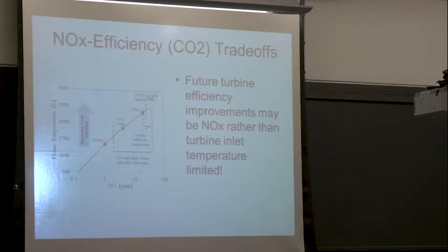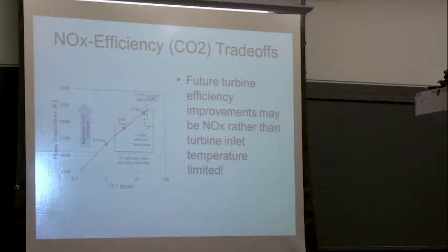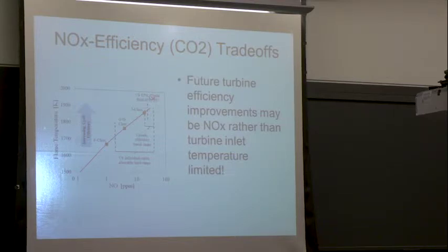And so now I think this is a great combustion problem: how do you turn off Zeldovich? So those of you who are doing high pressure, high temperature kinetics, what is it that you can do to somehow fundamentally change that sensitivity to temperature? Because, all right, well, let me just tell you, let's suppose I got to run at 1975 K.